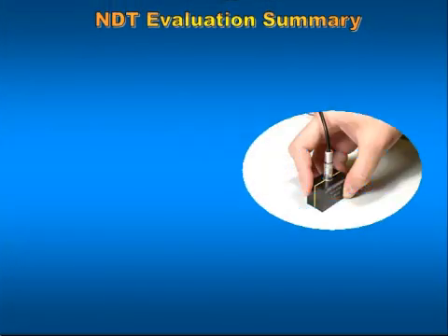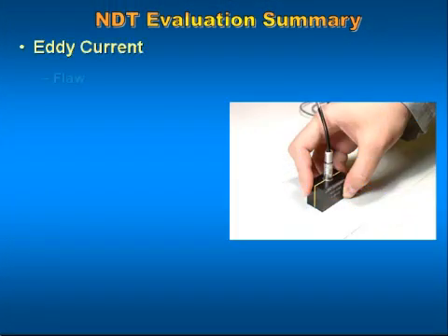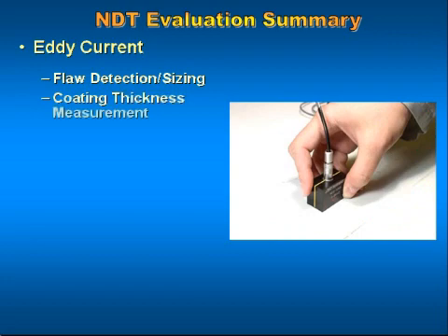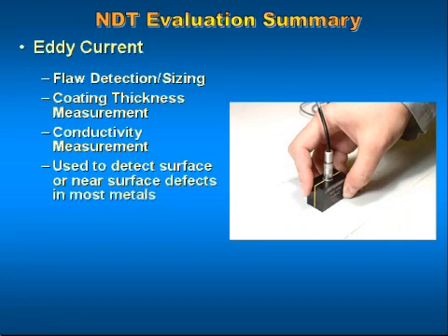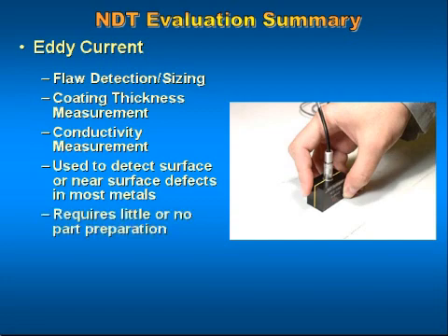Finally, there's eddy current testing. Eddy current testing is used for flaw detection sizing, coating thickness measurements, and conductivity measurements. It's used to detect surface or near surface defects in most metals, and the beauty of eddy current testing is that it requires little or no part preparation.